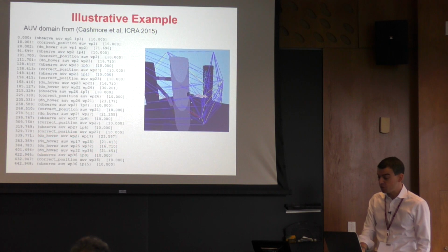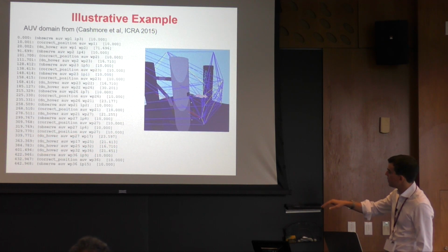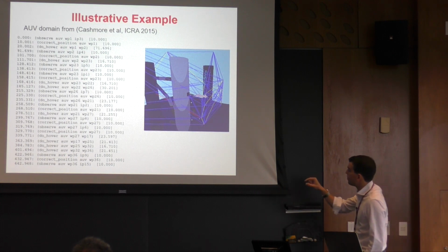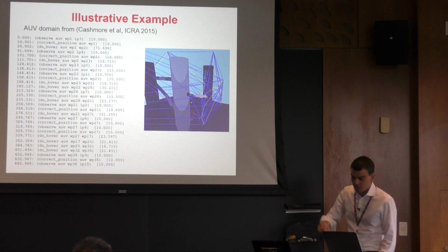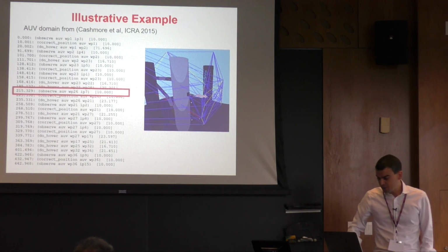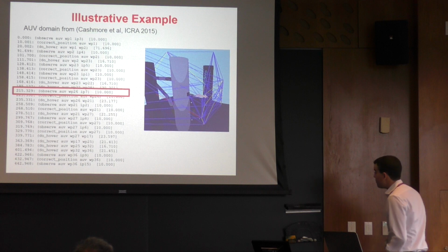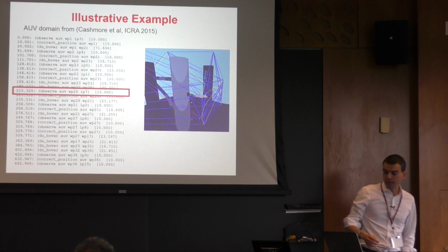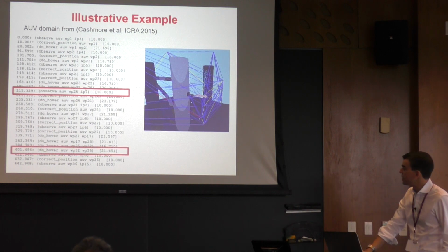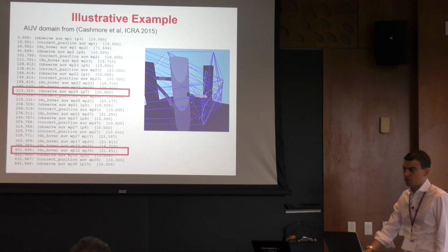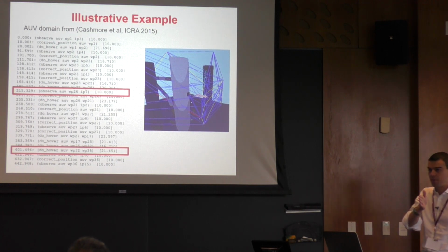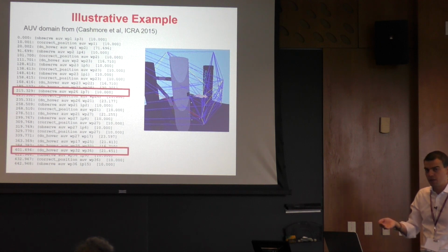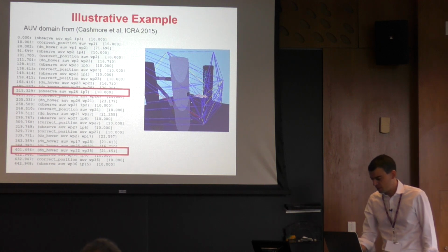This is an example for an AUV domain again. So, a longer plan, and here you see in blue the roadmap connecting all the waypoints. In yellow is the trajectory of the AUV. What happens is that at this time point, basically the AUV observed that there is an obstruction here because the map originally was not as accurate as expected. So you realize that that action in the plan can no longer be executed. So you discover much earlier that your plan is not going to be valid anymore, so you can trigger replanning in time and improve the situation.